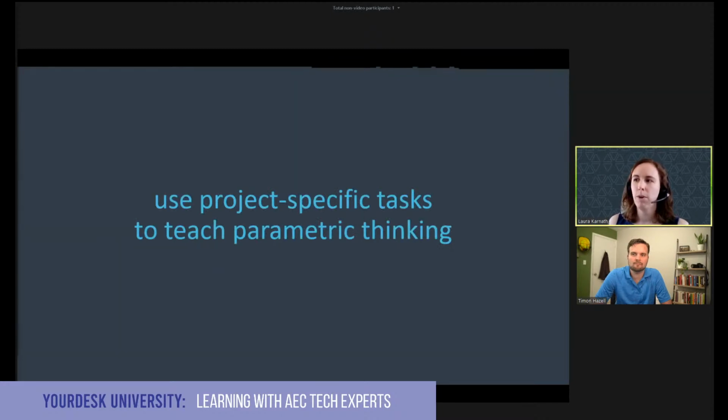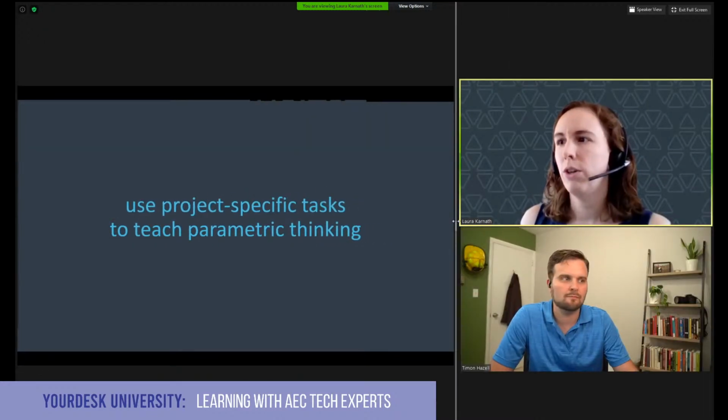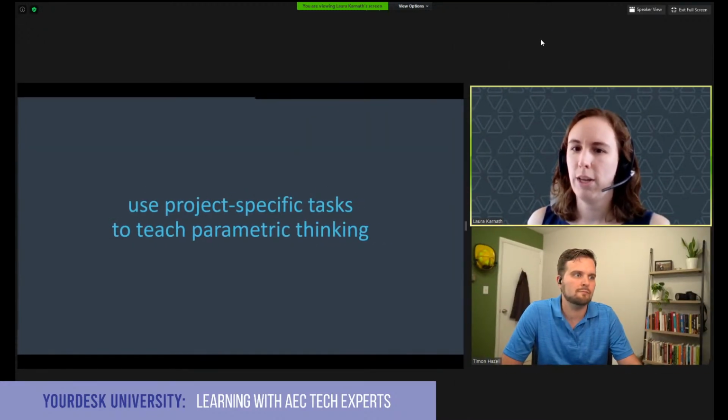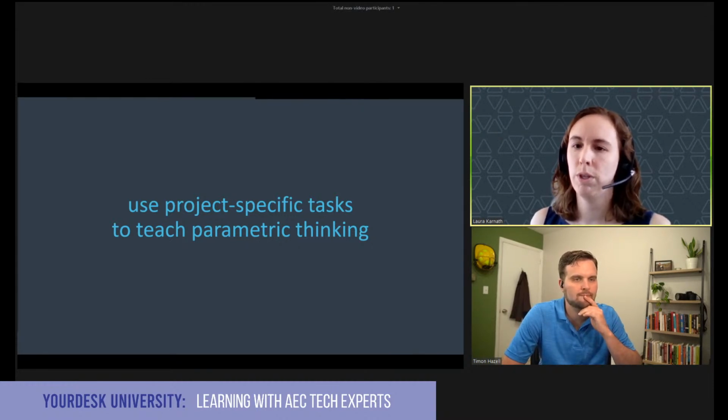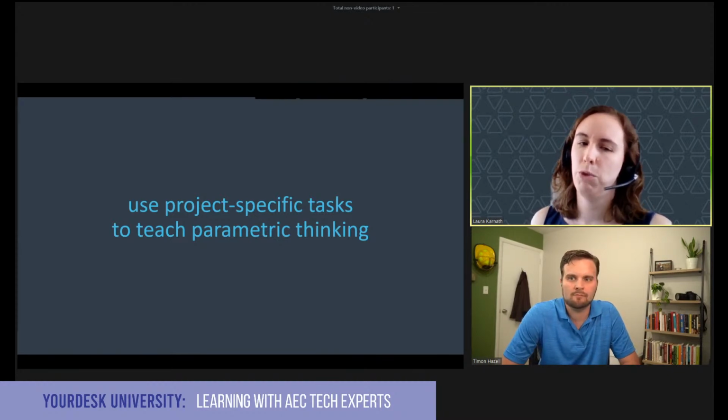So one of the things I wanted to talk about is using project-specific tasks to teach parametric thinking. People who don't have a lot of experience in Grasshopper or similar tools, it can be overwhelming to get started. So I start with them by creating really simple definitions and really simple tools, that I can then build complexity and flexibility and adaptability onto as the project moves forward and my team gets more experienced.